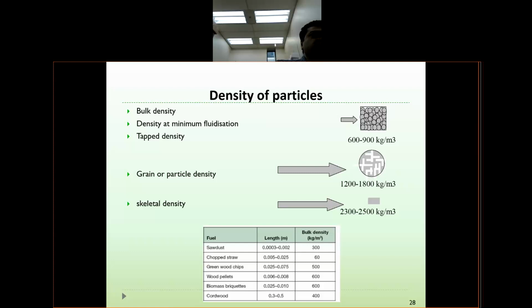Anyway, for those who don't understand French, broyage means grinding in French. But in grinding, even though it is important, it takes a lot of energy. It's a very energy demanding unit of operation. And people who design grinders have to be really careful to have a very good estimation of energy requirement in their grindings. And there are many designs of grinders.